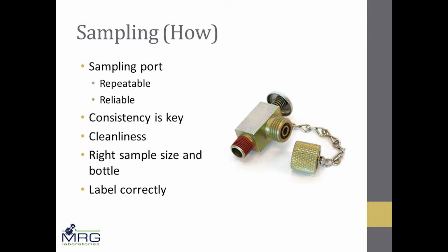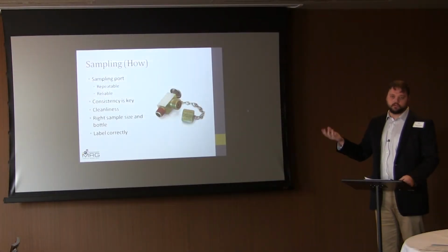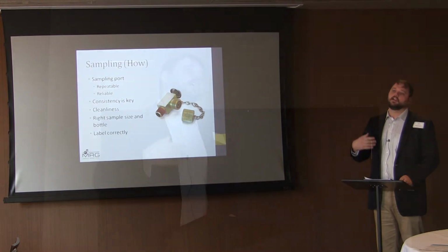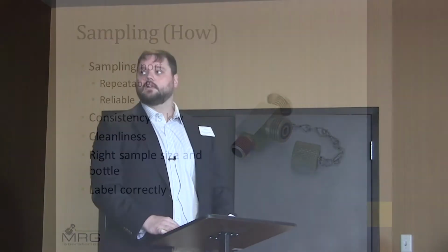Also, an important thing, like I said, with the vacuum bottle is the sampling size. When it comes to the lab, you want some headspace in the bottle, the reason being that we can then agitate the sample. If the sample is too full, we can't shake it properly, and then we can't ensure that the sample is homogeneous. So when we're analyzing it, we might be giving cues, and it's just that aliquot that we pulled out is bad, but the whole thing might not have been, and that hurts the analysis. So things like that, we want to work with the customer to make sure that they're going through the effort to get a sample, that they're getting value out of that analysis, that they're not just spending money to get analysis.